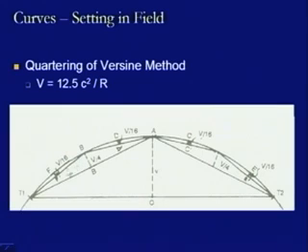Now, once again we have got another chord. On this one we can find the Versine, which will be 1/4 of the previous Versine, that is, the previous Versine is V by 4. So, the new Versine will be V by 16 and we will get another point, and this is how we can keep on going. Whatever accuracy we want, with respect to that accuracy we will go to a smaller value and we will have a smooth curve being drawn like this.